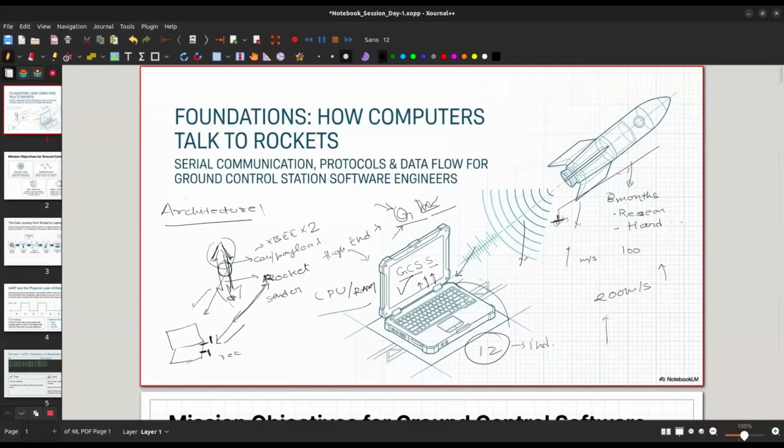You are going to send the data. You are going to receive the data at any time. And as in most of the competitions and most of the cases, even if you are doing it for your own interest, the requirement should be, or the requirement that is stated as, we need the telemetry as fast as 10 hertz, or maybe even 1 hertz. One hertz means they want the rocket telemetry to be updated at the portal at the rate of 1 hertz. Now that's a challenge for setting up the right kind of Zigbee as in hardware.